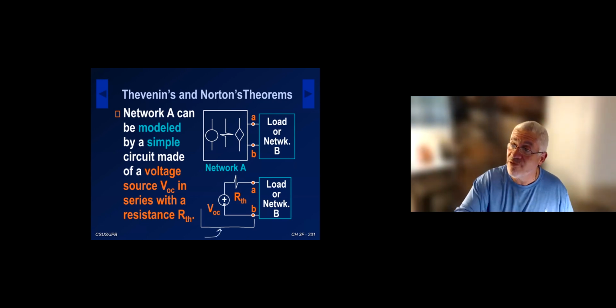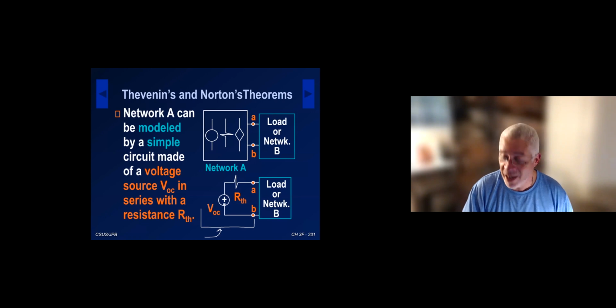So if you are asked for a Thevenin model, the first thing you do is draw the model, which is very simple: the independent voltage source in series with the Thevenin resistance. The voltage source value is VOC. Okay, and then the next two steps are to calculate VOC and calculate the Thevenin resistance. So these are the three things that will be implied when you ask a problem, give the Thevenin model about a particular circuit. Okay, so we're going to practice this, but first we're going to learn how to find VOC and how do we find the Thevenin resistance.